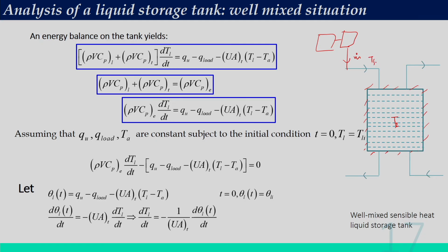And maybe this TFO is the fluid outlet temperature of the collector, which is introduced into the insulated tank, and this TFI, which is equal to TL, will be introduced again into the collector. And maybe m dot load I will write, which is connected to the load, so that we can use it, and this may be Ti, and Ta is the ambient temperature. Okay. And this temperature is at TL. Okay. So, here TL is the delivery temperature.